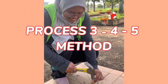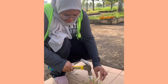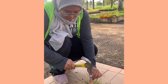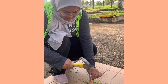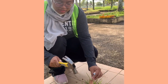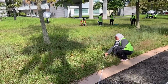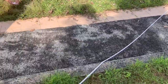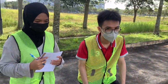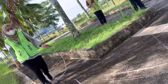Process 3, 4, 5 method. Once the location of the building wall is marked, action must be taken to preserve these marks. The spikes are set up around the building line at a distance of at least 1.2 meters from that line. Next, determine the location of the boundary stones and make sure of the direction of the building. After that, determine the location of the main building line by measuring from the stone border.